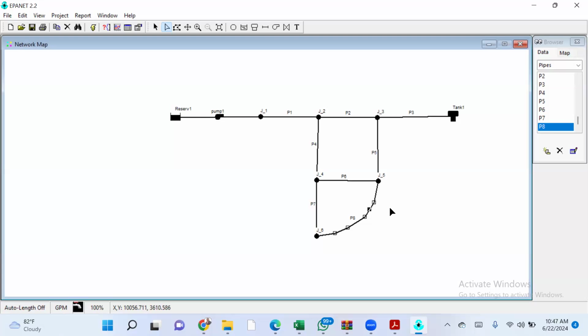Sir, I want to ask a question. Can you remove the vertex after making your curvature? No, it will go out on its own. You know what I'm saying? Because my own added vertices are so close together, I can't even adjust. You can drag them up. Use the cursor on the vertex, hold it, click it to highlight, then drag it to the point you want.